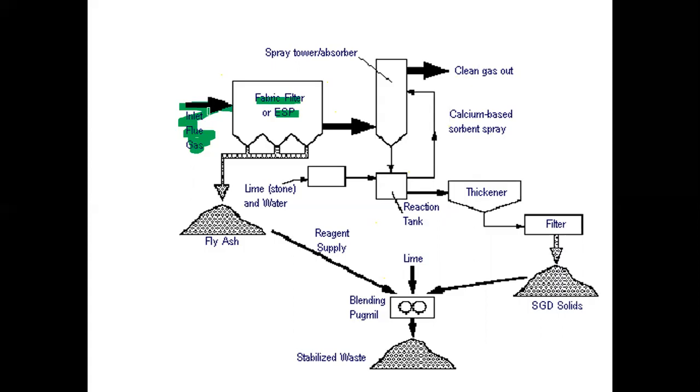Then what happens? The suspended particles, there may be unburned fuel particles, unburned carbon particles, will remain in the bag, and the particle-free gas will go out from the fabric filter.